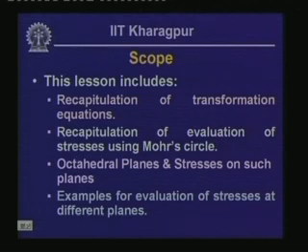Hence, the scope of this particular lesson includes the recapitulation of transformation equations which we have derived in the last lesson, recapitulation of evaluation of stresses using Mohr circle. We will be looking into some aspects of octahedral stresses. We will define octahedral plane and the stresses acting on such planes, and then we will be looking into some examples how to evaluate the stresses at a particular point on a stressed body.